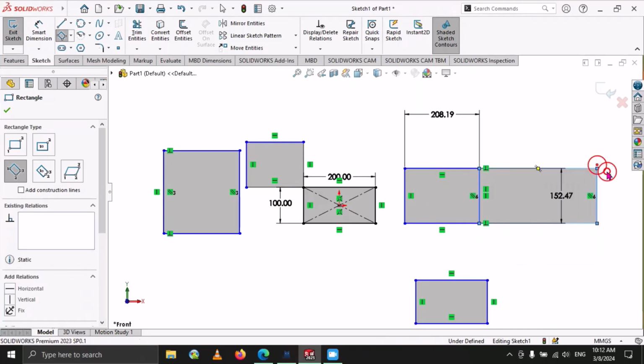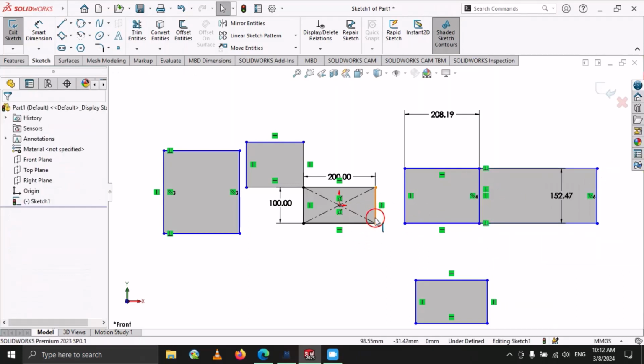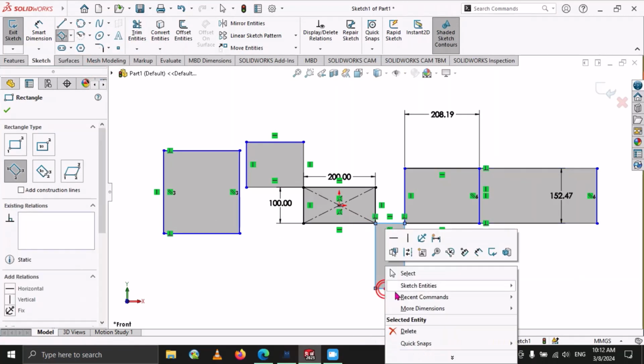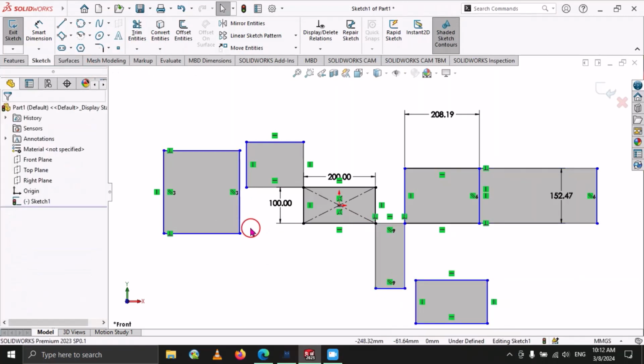Okay, so we can select this corner, and then go to the right side. See, and similarly let's suppose we want to draw a rectangle between these 2 points. So for that we can also use 3 point. So we can select this point, we can select this point, and then go down. So that's why different options are available. It depends upon the complexity and the situation of the sketch that we are going to draw. So therefore they provide the different methods.